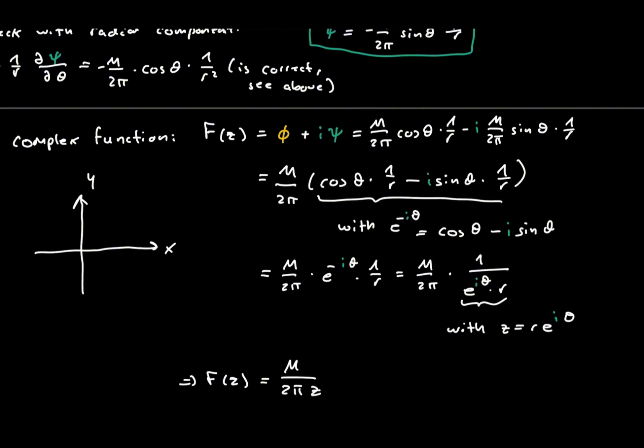Physically, this flow is directional. Fluid approaches from one side and leaves on the other. This is why the dipole is so useful. When we later combine it with a uniform flow, we can model flow around bodies like cylinders.